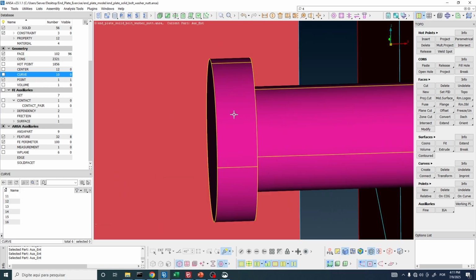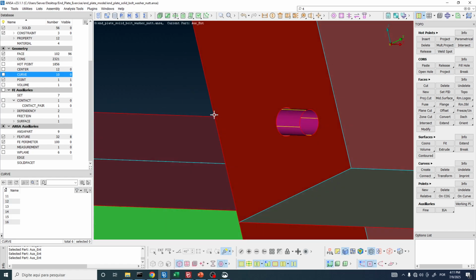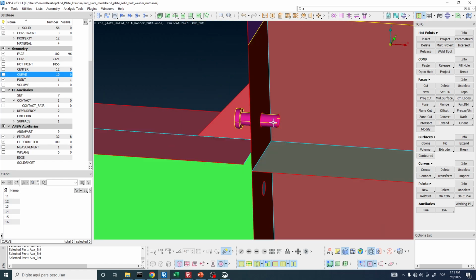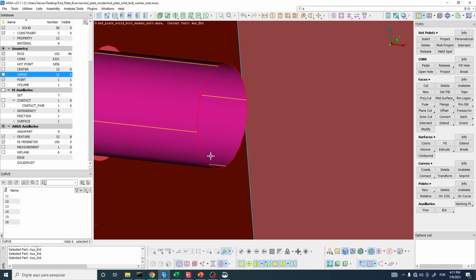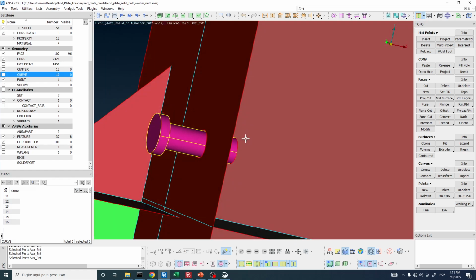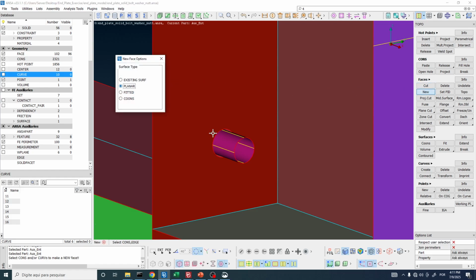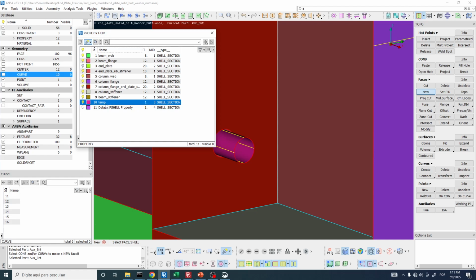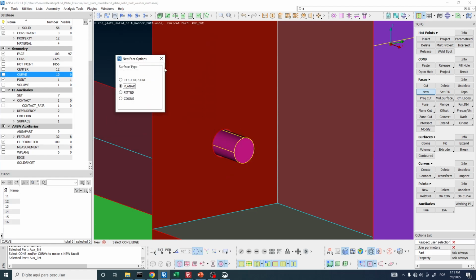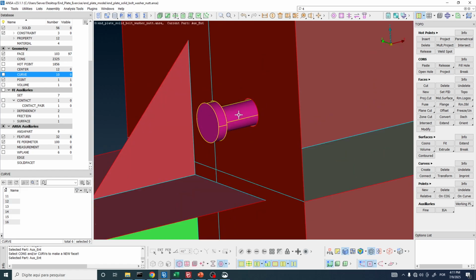Yeah, the thickness of this bolt head is looking really weird, right? But that's okay. We're going to modify it later. Now we need to close here, to close this volume, right? I need to create a closed volume. So new face planar, loop selection mode, select this, middle mouse button, auxiliaries, temp. Okay. Close. And here we have the bolt.